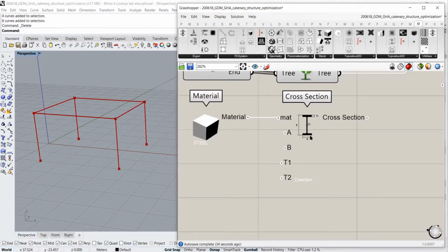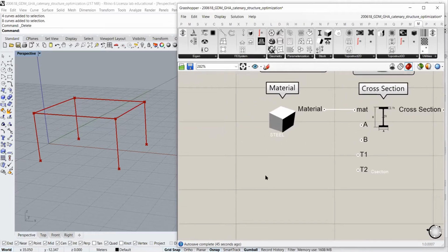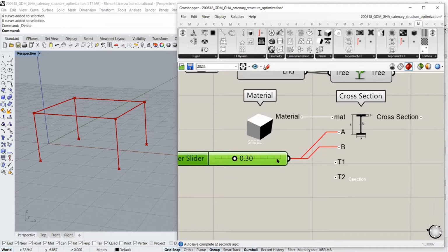Now, in this case, A is the width of our cross-section. I would create a square-ish beam or square-ish cross-section in this case. So A and B are going to be the same value for the columns. I'm going to use something like 0.30 in order to reach up to 1 meter if you want. This is quite a huge structure. We have more or less an 18-meter span in this direction. So it's quite a huge span. So let's give this the proper range. And I'm going to use this as A and B at the same time. So it's going to be a square column, basically.